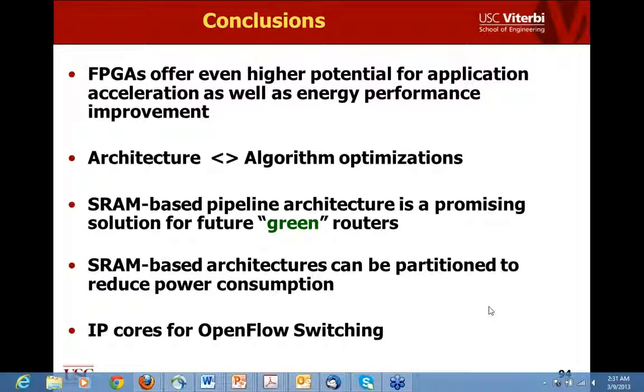That particular stage, conceptually, is going to be mapped into the logic resources we have, and the connections between the pipeline stages are going to be performed using the routing resources we have on the FPGA device. So whatever we talk about conceptually is actually realized by using lookup tables and the routing resources, and either the distributed RAM or the block RAM for implementing the memory in those systems. I see. Okay. Thank you.